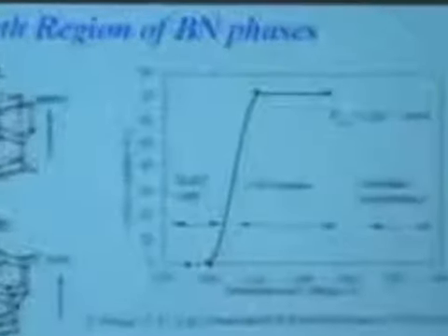So if you do so, we found that there is a regime. If you apply your bias voltage too high, all the atoms that reach the substrate will bounce away, sputtering. All right? So this regime we call the total film resputtering regime, which means if you put a chip on the substrate and apply very high bias voltage, after 10 hours you take your chip out and you find that nothing has been grown on the chip. Everything deposited will bounce away. We found that we can grow these boron nitride tubes in this no-growth region.